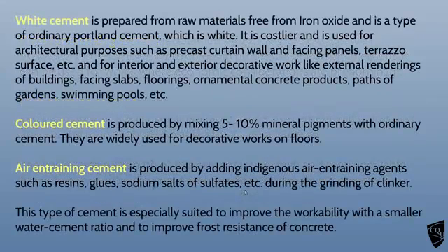White cement, well, that's for cement that you're going to see, basically. Your coloured cement, pigment it, obviously. The air entraining cement is interesting. You can add glues and resins and sulfates when you're grinding it up, and it's very workable, easy to use, with less water in it, and it's very frost resistant as well. So cold climates maybe.